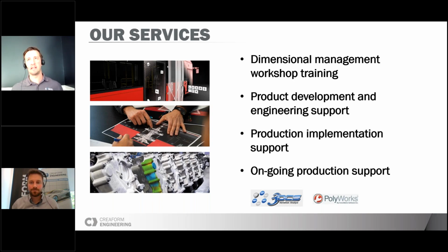Even in 3DCS, we showed a lot of CAD because it's a big benefit of the software, but if you have some preliminary geometry, just points, lines, or sketches, you can already start to make those lines and points vary or deviate in the environment and see what the impact would be. The sooner the better, because as soon as you find the problems, you can modify your design accordingly.